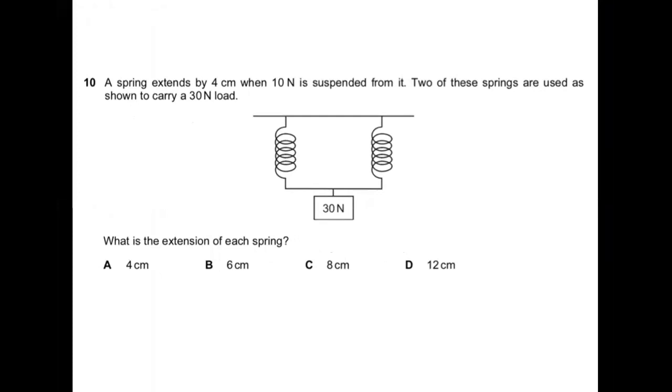But over here we have two springs in parallel. So the load will be divided between each spring equally. So 15 Newton will be the force exerted on this spring and 15 will be on the other spring.